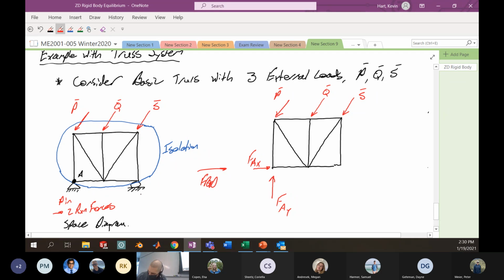That differs from this reaction force over here. And this symbol has a very specific meaning in engineering as well. This here is called a roller. And this is one reaction force. In this particular situation, let's call this point B. You would represent what's happening at that location with something like force at B in Y. Notice here I haven't added the X force, and that's because this particular type of reaction would not call for that resistance in that direction.